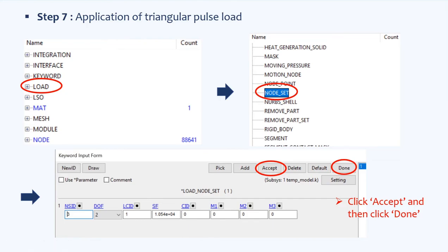Okay, one more thing. How you calculate this scale factor is also important. For the blast loading that we have considered, it is a 6 kg charge mass kept at a standoff distance of 1.81 meter, for which the reflected pressure comes around 4.27 if you calculate using the KB chart.